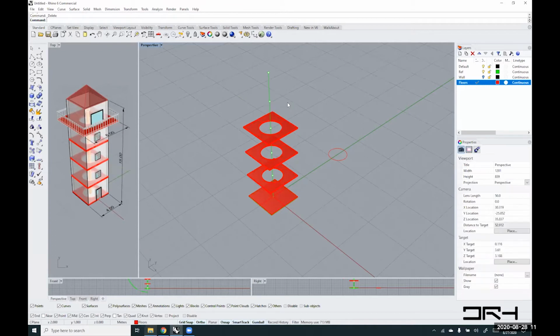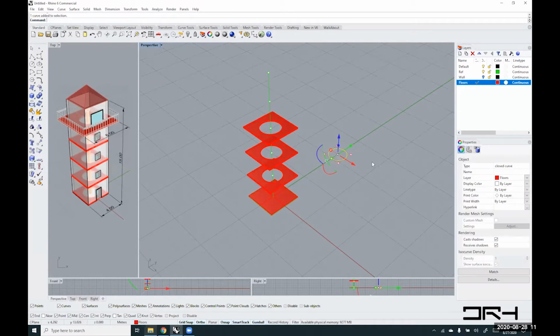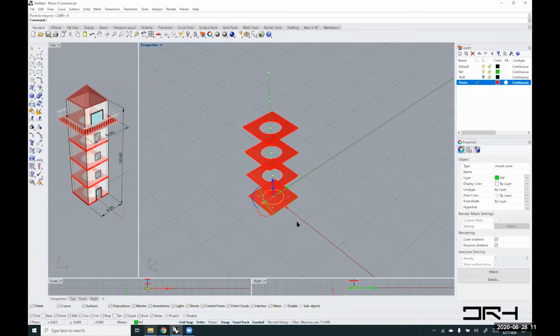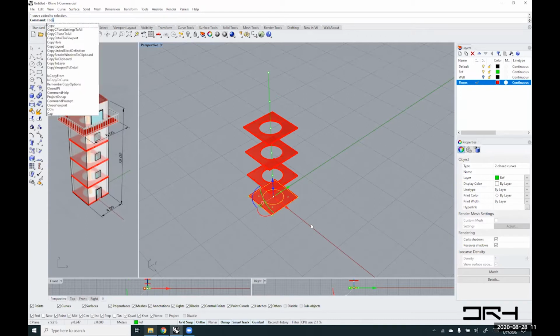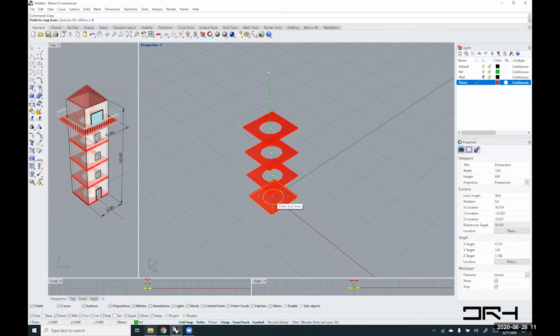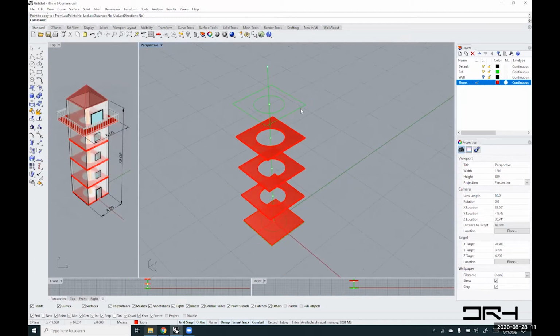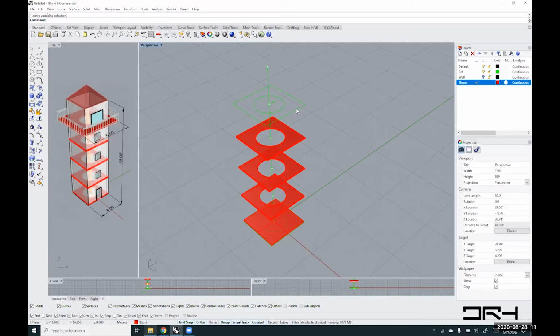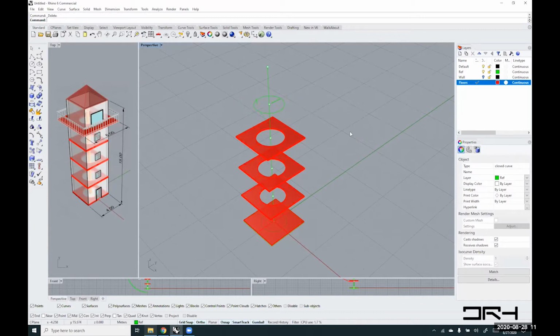So I'll just delete this guy. And remember that, I'll move my circle here. I'll put it in the scaffolding as well, and I'll move it from the center of it to 0. If I copy that circle and the rectangle curve vertically from 0 to this point, now I have some reference geometry that I can use, but I want to scale this so that it will be the size of the deck, which is 6 meters. Another thing I can do is just recreate that, which might be even easier than scaling. So I'll just delete that actually.